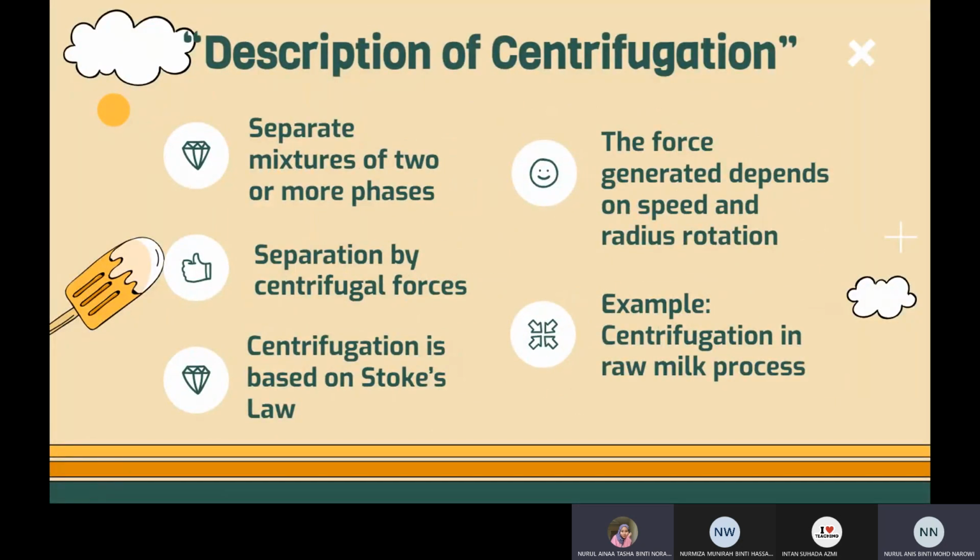First, this process is used to separate a mixture of two or more phases, and one of the phases must be in continuous space. Next, this separation is done by centrifugal force that provides different driving force based on the density of the phases themselves. Third, this process is based on Stokes' law, where the particle sedimentation velocity increases with increasing diameter, increasing difference in density between the two phases, and decreasing viscosity of the continuous phase.